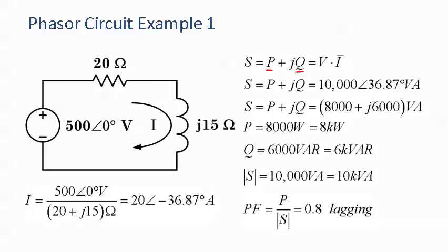The way to calculate the whole thing, the complex power S, would be to take the voltage, phasor RMS voltage, times the conjugate of the phasor RMS current. Now here in this notation, I'm not using the little tildes anymore, and the bar across the current means that it's the complex conjugate of the actual current.